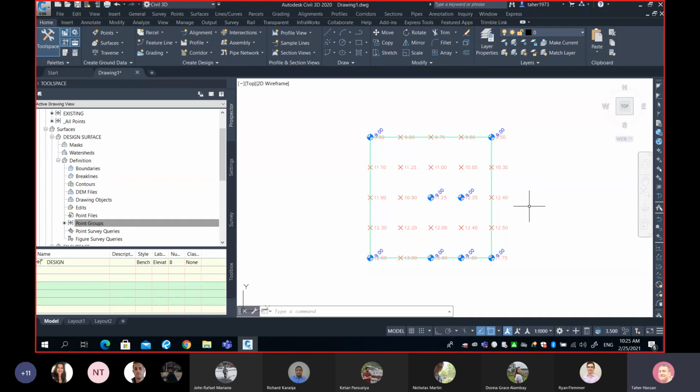Even if you make your contour interval so tiny, it is a flat surface. It means it will never be intersected. Actually, there is only one contour line, which is the boundary. So the boundary is also contour line number 9. It's a flat surface, so no matter what you do with the contour interval, it doesn't show any contour line, because it's a completely horizontal surface.